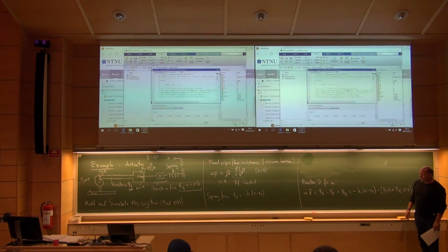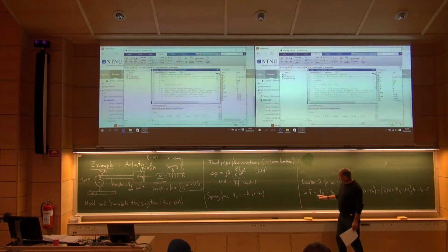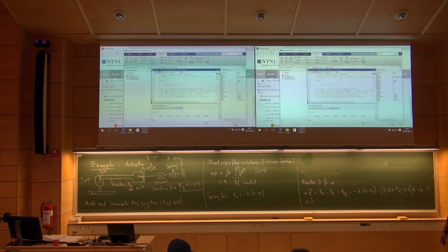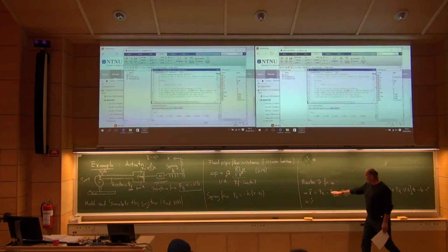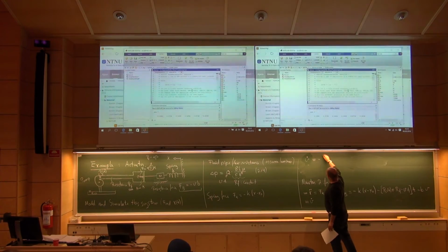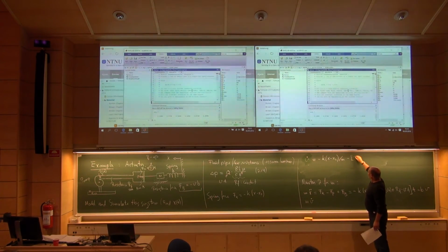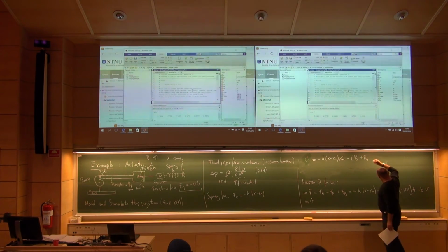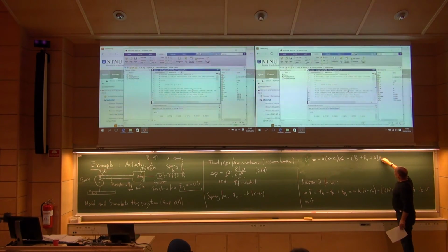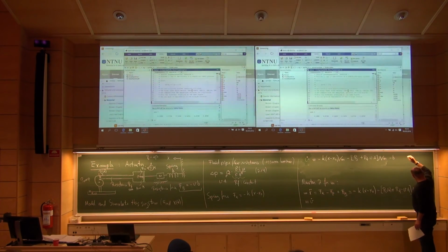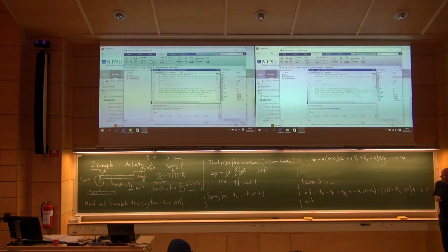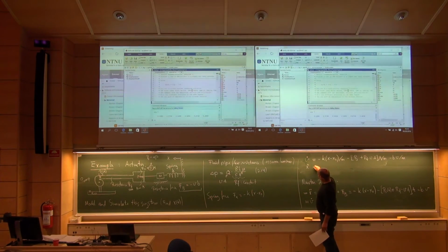Rewrite this equation here as a set of first order equations. Well, here we can do it a little bit physically. This mass times acceleration you can write as mass times the velocity derivative. That's the same. So we can use velocity as one unknown. Then I'll write this equation on the form v dot equals. Just divide by m, and then we get minus k (x minus x0) divided by m, minus the drag term, plus rf times v times A divided by m, and finally the velocity divided by m. And then we have one more equation, say x dot equals v.